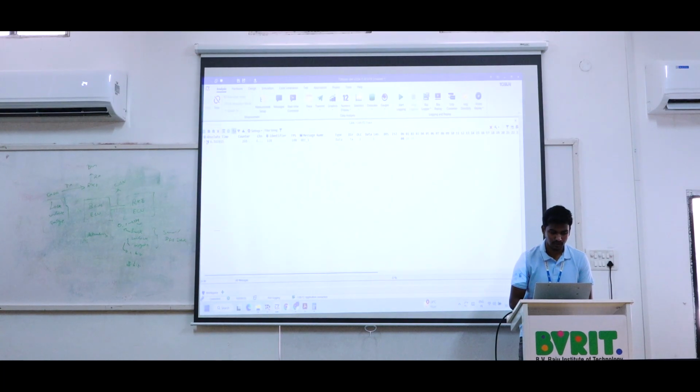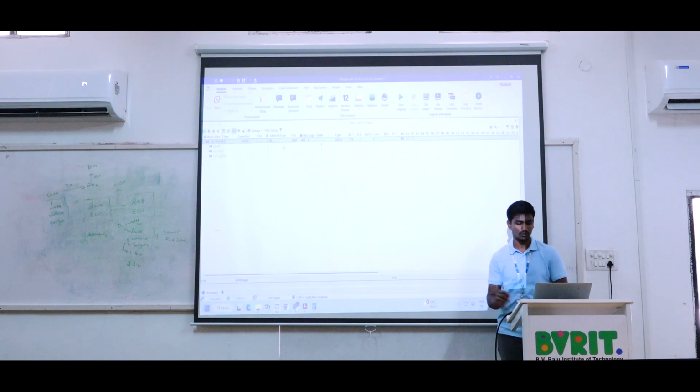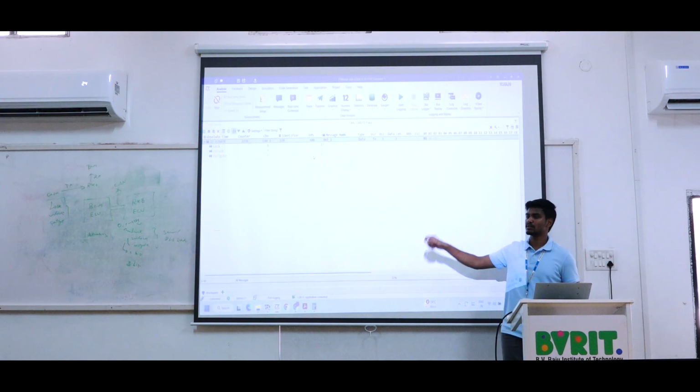This is the trace window I mentioned. Here we are going to check for the signals. It is showing signal value 0101, with identifier number 120. So we just transmitted only ID number 120. Here we need to set some channels. FPS is nothing but frames per second, that is, how many times per second this message will be transmitted.